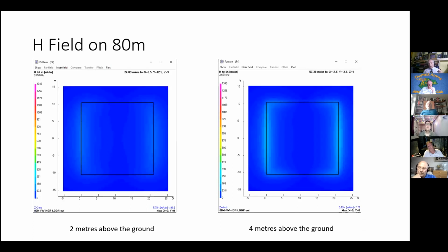What I've modeled over ground for 100 watt level stations is that you need somewhere between 0.5 and 1 meter of separation if the wire is above the ground. Probably 0.5 meter is enough at 100 watts. And I figure that burying it by that much leaves a big safety margin because the field will actually stay closer to the wire under the ground. But it does depend on the ground. If it's sandy soil, or pure dry sand, it might as well not be there.